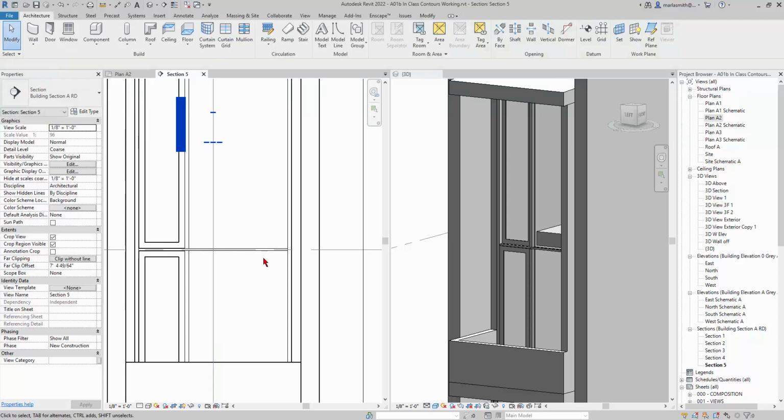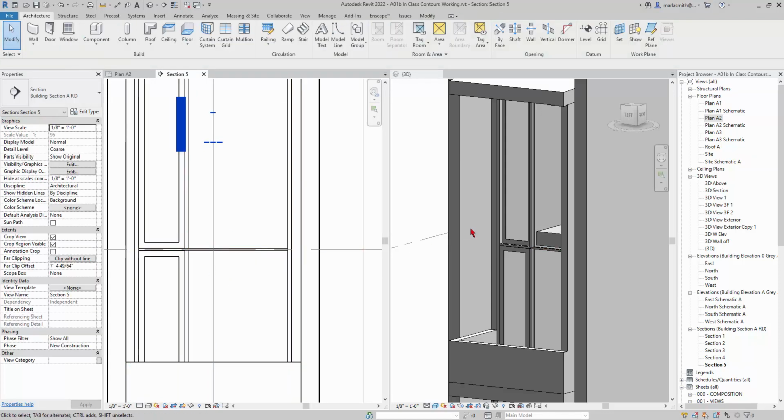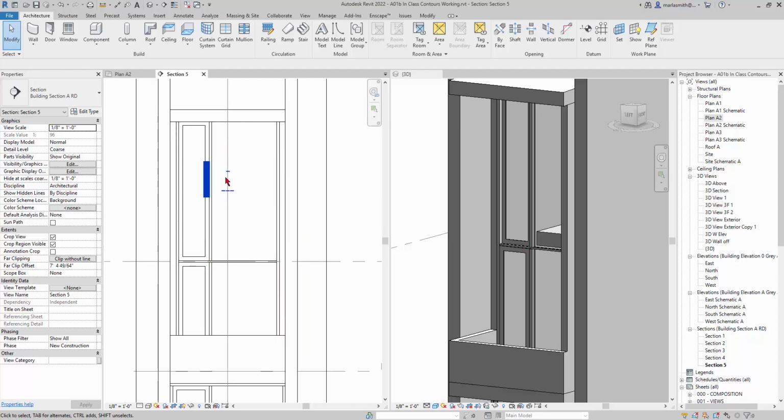in there. So you can see the mullion, and if you tab select in, you can pick that mullion, and see that it's created that mullion. Now we have a mullion here. We have a piece of glass above it, and we have the world's biggest, tallest door to nowhere. You can't get to it. So let's go ahead and get rid of this door.